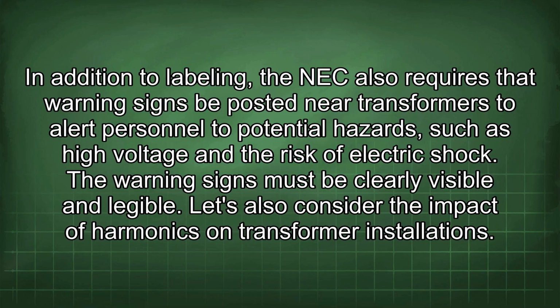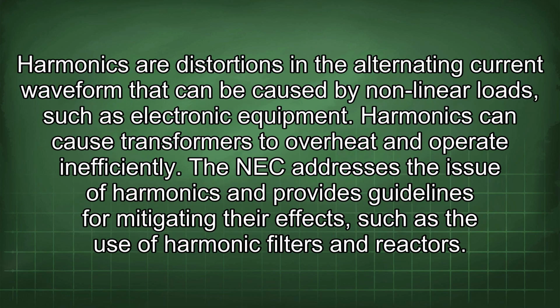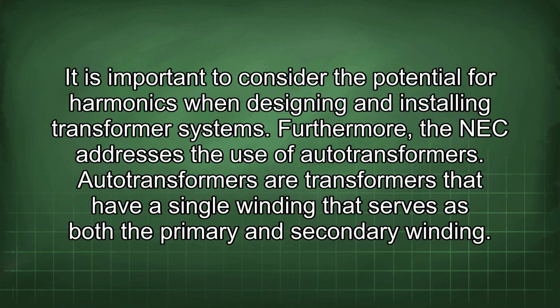Let's also consider the impact of harmonics on transformer installations. Harmonics are distortions in the alternating current waveform that can be caused by nonlinear loads such as electronic equipment. Harmonics can cause transformers to overheat and operate inefficiently. The NEC addresses the issue of harmonics and provides guidelines for mitigating their effects, such as the use of harmonic filters and reactors. It is important to consider the potential for harmonics when designing and installing transformer systems. Furthermore, the NEC addresses the use of autotransformers.